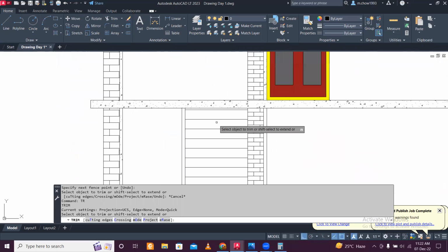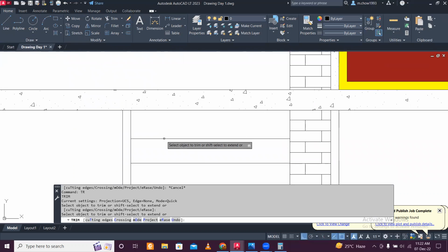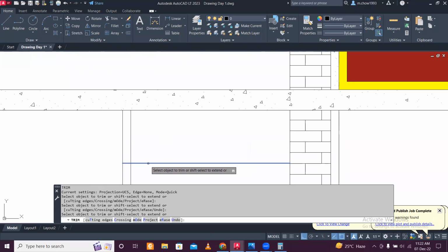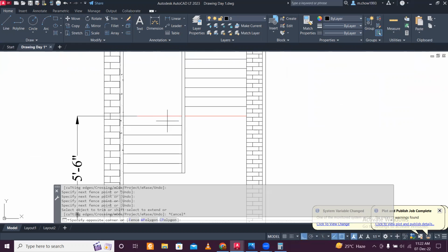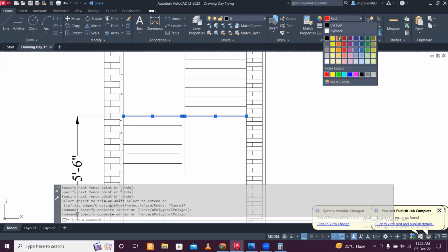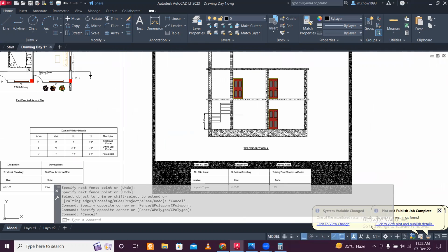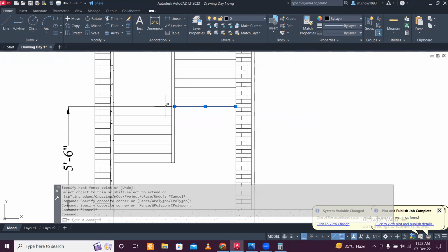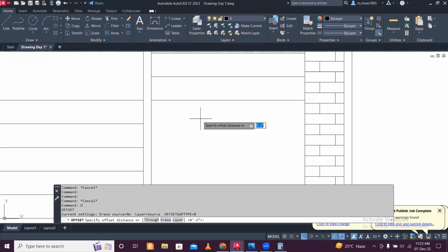Last 3 steps. So remember, the last step is merged with the slab. So this is 1, and the second step, if we do not see this, 2, and then 3. This is the third step which we will not see. So we'll see up to this. So shift and then extend this, and then we can delete the gap here as well. So this is the portion which will be visible. Landing is here. You can select this and now do this 5 here. So this is the mid landing portion, and this is the portion which will be visible here. And you can also denote the landing slab which will be there, because this is also slab. Let's go for a 6 or 7 inch landing slab. Okay, 7-inch landing slab.